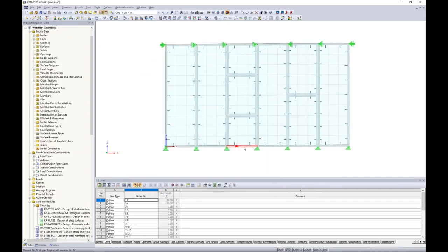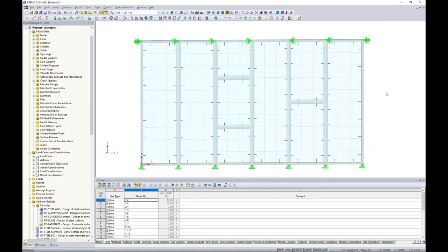And I can see here that my FE mesh is a little bit too large. I only have 3 FE mesh points along the width of these glass panels. This really just isn't ideal to give us accurate results. So it's always suggested that we need to go smaller than this. Now this will increase our solution time slightly, but in turn, of course, we need to see accurate results.